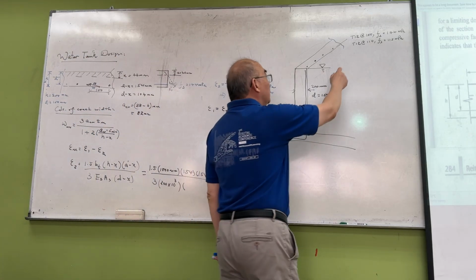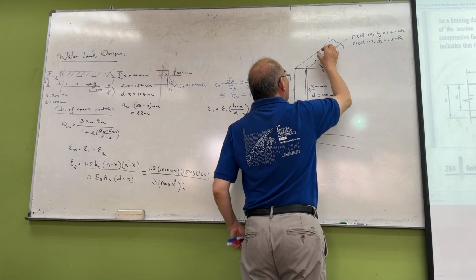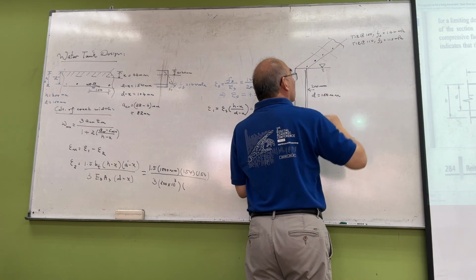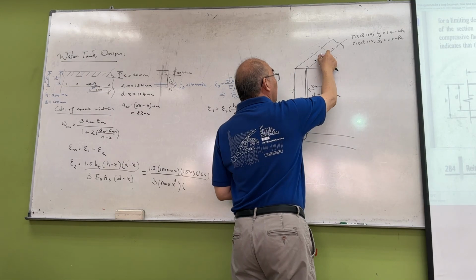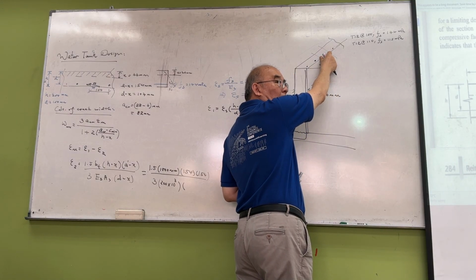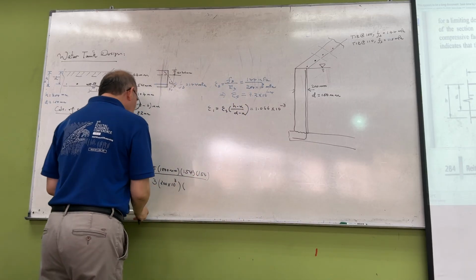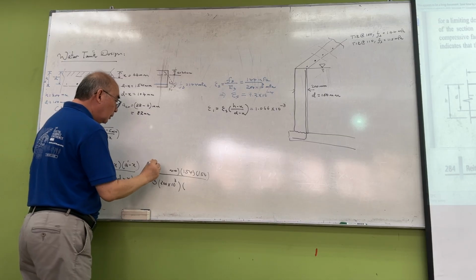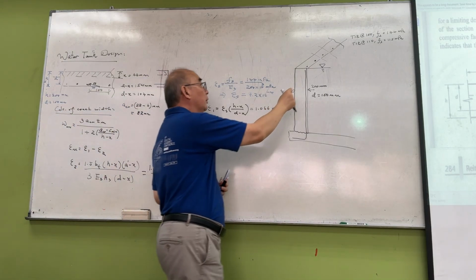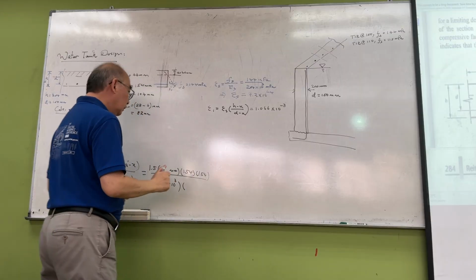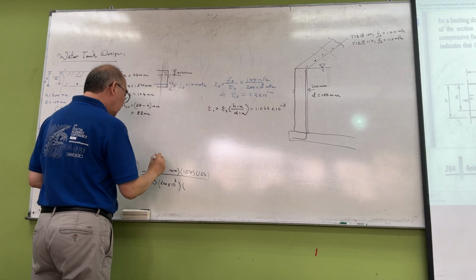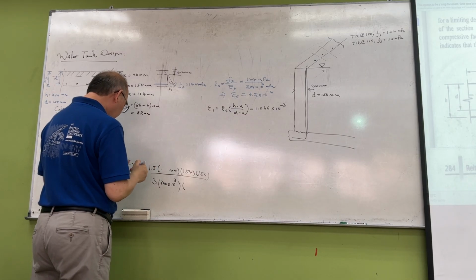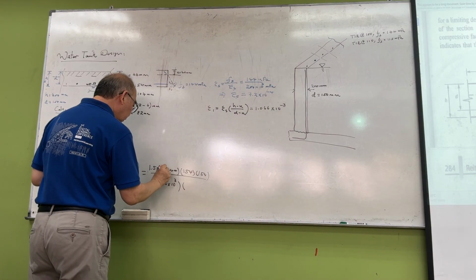Because we are doing T12 at 150, instead of doing 1000, I base it on the spacing of the rebar, in this case 150.